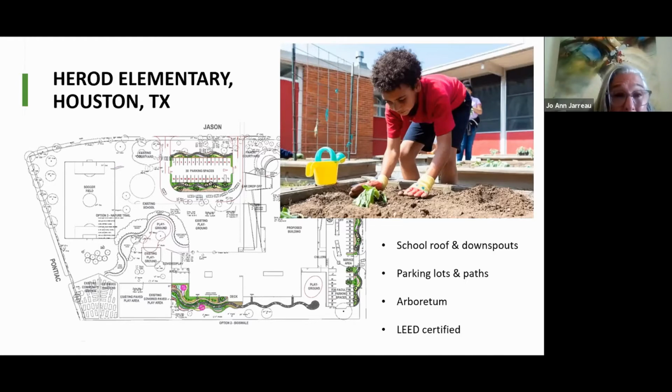But also, I wanted to say, Ruhina, that what is really very important to do in these parking lots is to have these curb cuts. And as you can see, I have those cuts in certain places where the gravel is coming in, so it's conveyed into the bioswales.